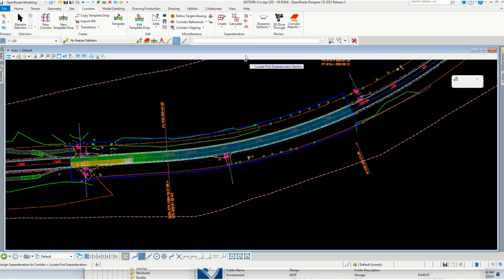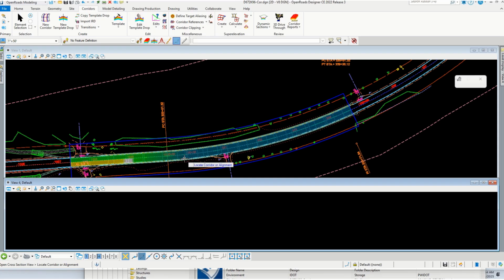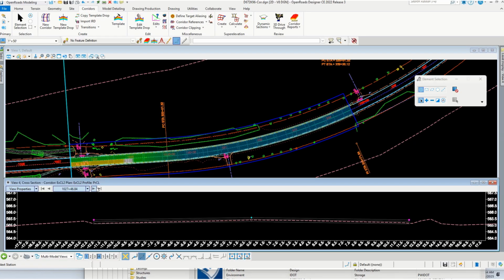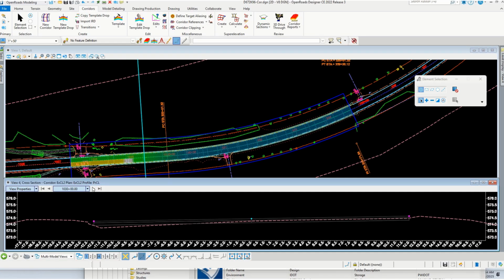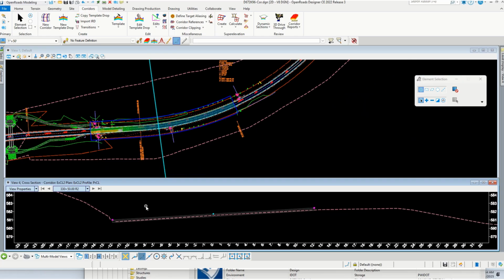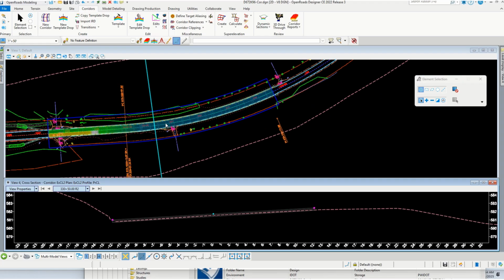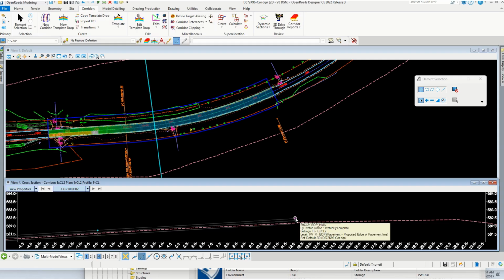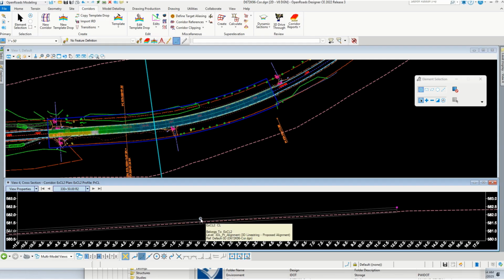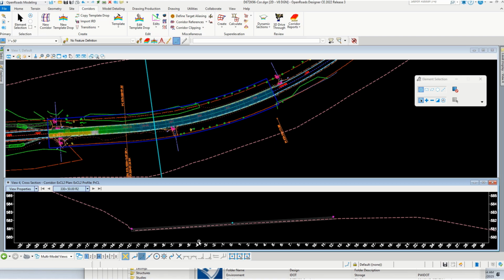Let's go ahead and create a dynamic cross section, or visualize a cross section, by clicking on that corridor, choosing a view, and toggling through. There we go. And the way that you can tell that we've overwritten those points is, see how it's a pink point now on each end, and a blue one at the middle? That's the pivot. You can see that the cross slope is no longer 1.5%.